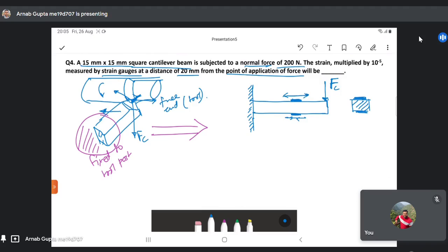From this extent of expansion, which can be defined as strain, it may be related to the force which is acting. If you are able to calculate this value of strain by measuring the voltage changes, then you can fairly estimate the value of the force using some calibration principles.